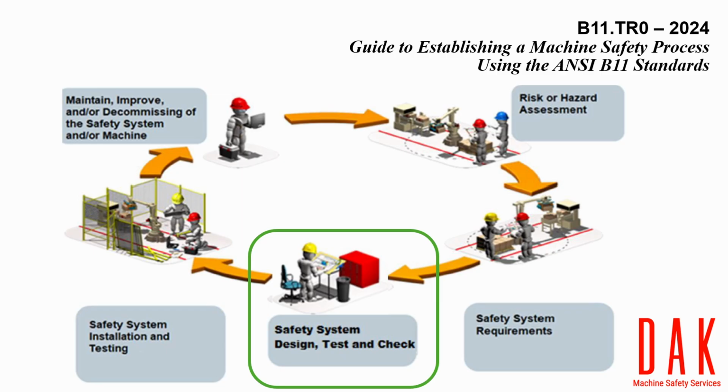Testing of the design is necessary to ensure the safety system functions appropriately. The testing activities may take different forms due to machine type and the risk mitigation techniques that are installed. It is important during the design phase of the life cycle to provide test methods and designs that help prevent unnecessary risk from being taken during testing activities. Checking the design to meet the safety requirement specification is an important step. This confirms that the design meets all of the safety requirements for risk reduction, such that additional hardware or software does not need to be installed during testing.